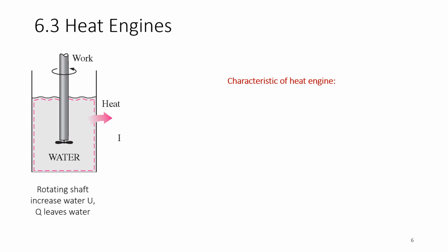Okay, so let's proceed with the next topic. We have so far covered the introduction to chapter 6, which is the second law of thermodynamics, and you have seen the definition of thermal energy reservoirs. We have the source, which supplies heat, and the sink, which absorbs or receives heat. The important feature of the reservoir is that while it supplies and absorbs heat, its own temperature remains constant. Okay, so now we come to heat engine.